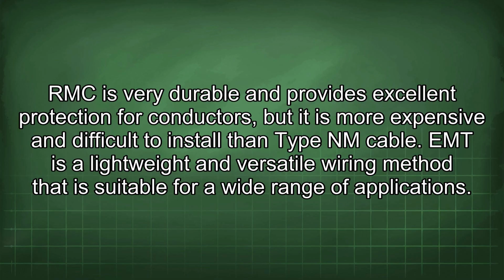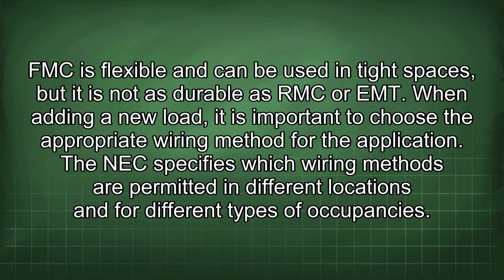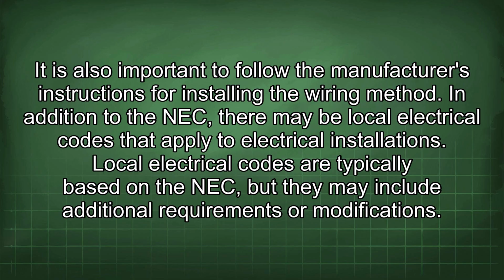EMT is a lightweight and versatile wiring method that is suitable for a wide range of applications. FMC is flexible and can be used in tight spaces, but it is not as durable as RMC or EMT. When adding a new load, it is important to choose the appropriate wiring method for the application. The NEC specifies which wiring methods are permitted in different locations and for different types of occupancies. It is also important to follow the manufacturer's instructions for installing the wiring method.